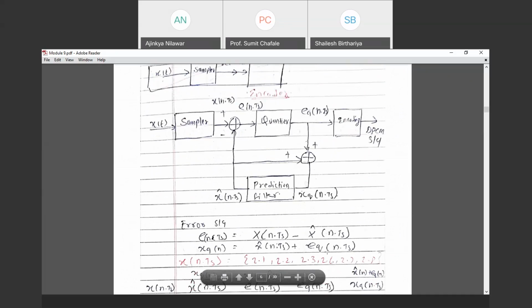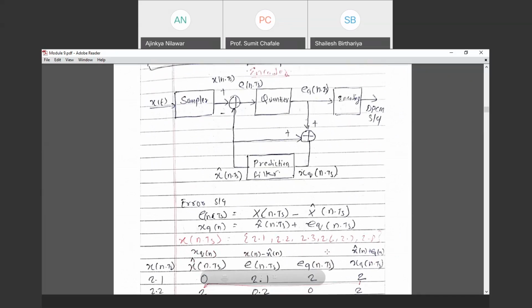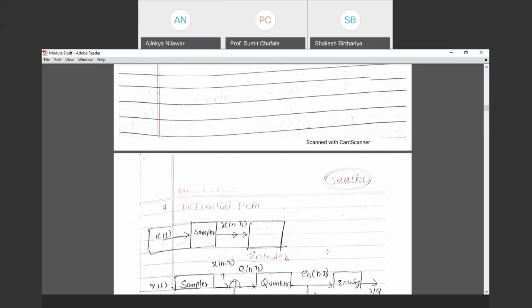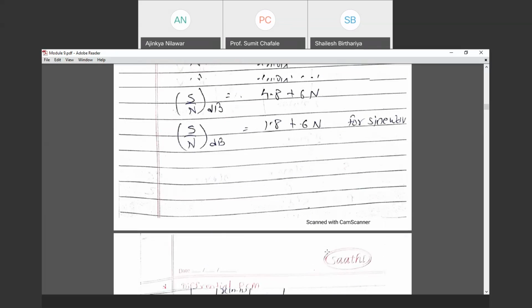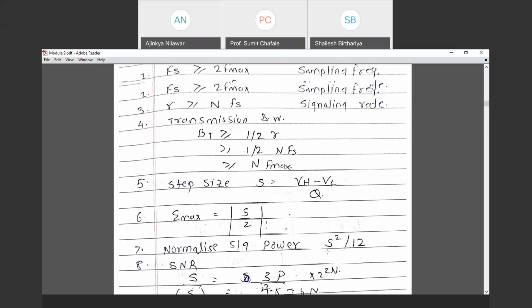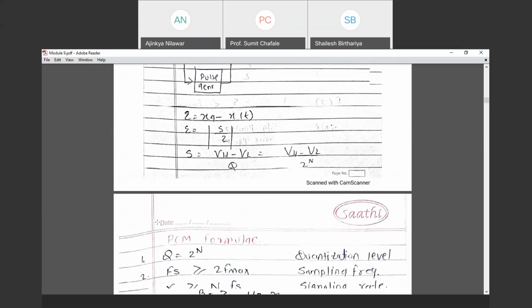PCM. Now, the next technique is differential PCM. So one may ask the question, why is there a different technique if PCM works better? You know that it depends on the number of bits. Suppose the value of n is 3, with a 3 bit input, n is 4 with a 4 bit input, and n is 5 with a 5 bit input. That means for this signal only these many bits get generated, and the number of bits is more, the bandwidth requirement is more, right?